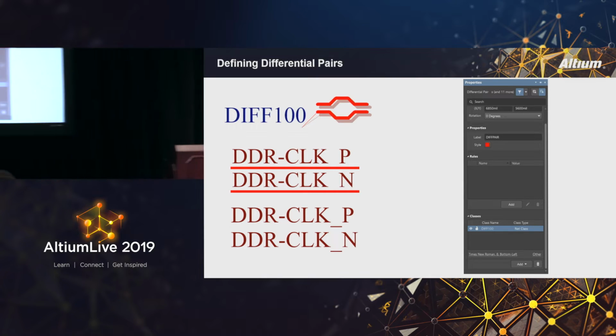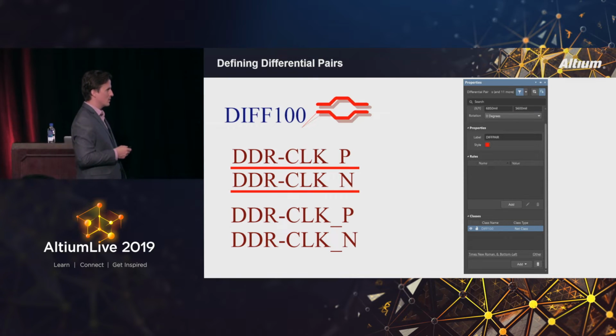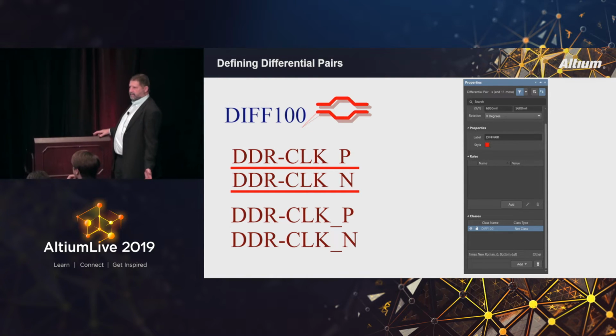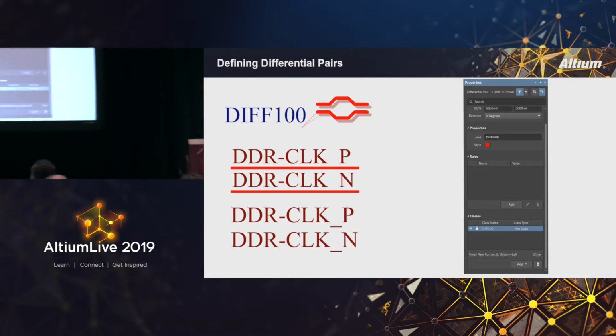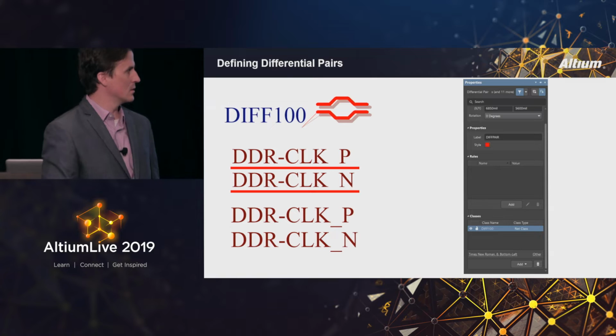Here we're going to set up, and you can talk about this a little bit, and then I've just got one point I want to make about it. Obviously _P and _N denote a differential pair, and that's how Altium likes to see it across the board. You can set that up differently in the PCB, but why would you? The schematic should be driving this, and then we put that differential pair directive on it, and it comes in as a differential pair class based on that. Thanks to a feature specified, you can now drive it to their class. Yes, right. We definitely want to do that.